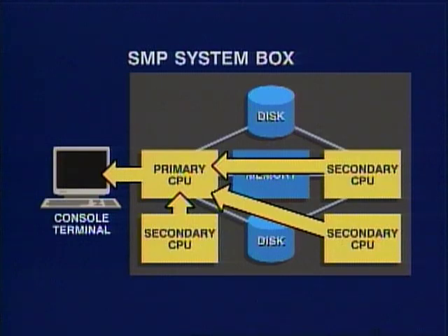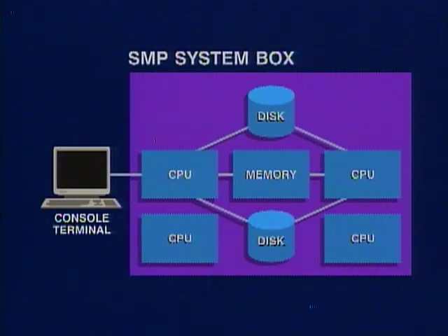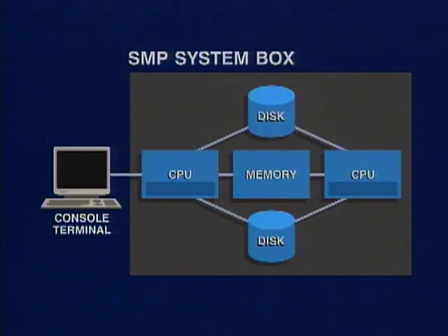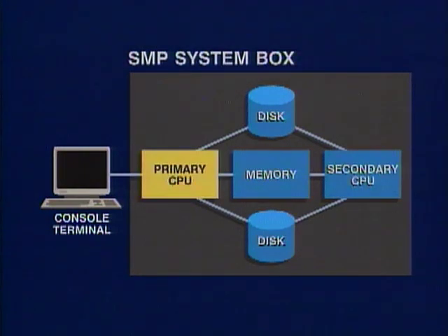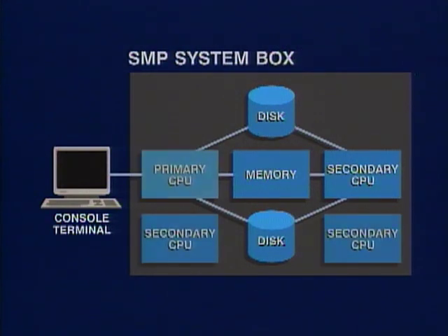The primary processor is selected when the system is initialized at power-up. Typically, the primary processor is the processor with the lowest CPU identifier. In the case of two processors, for example, one with a CPU ID of 0 and the other with a CPU ID of 1, the processor with a CPU ID of 0 is usually selected as the primary processor. In the VAXstation 3520-3540, CPU ID is determined by the backplane slot.